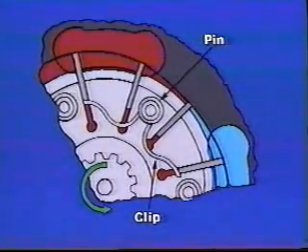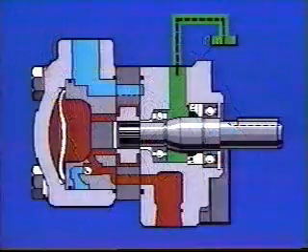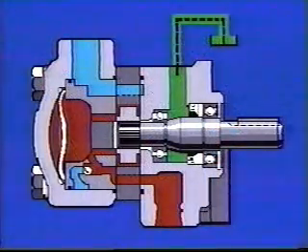With two vanes 90 degrees apart, when one vane is moving out of its slot, the other one is moving in, giving us a rocking action which minimizes the flexing of the spring, increasing its life. This is another view of the rocker arm motor.